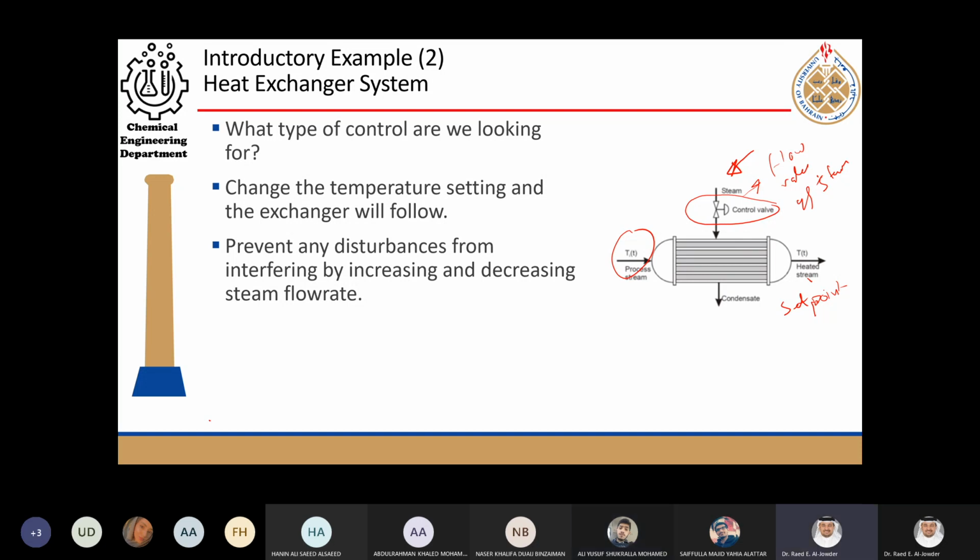Yeah. So energy basically here is supplied to the system in terms of steam flow rate. Energy Q is supplied. So it's basically M, mass of steam, times Cp, heat capacity of steam, times delta T. Or, because we are operating at constant temperature, the temperature does not change, it will be UA delta T, or it could also be a function of lambda.